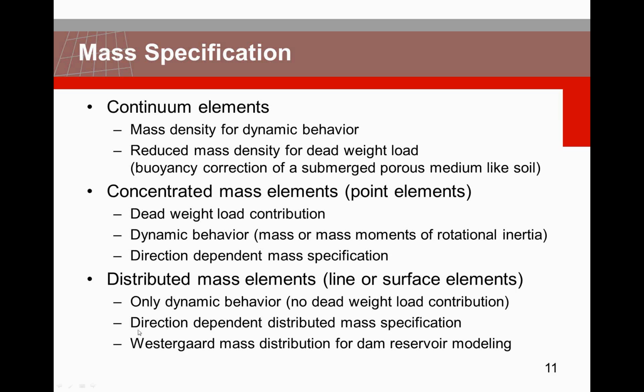Also, these elements can be defined in a direction dependent way, and there is a special application, a special mass distribution, the so-called Westergaard mass distribution, that will be of interest for the people doing a dam analysis, because this is a typical mass distribution of the fluid acting on a vertical dam.